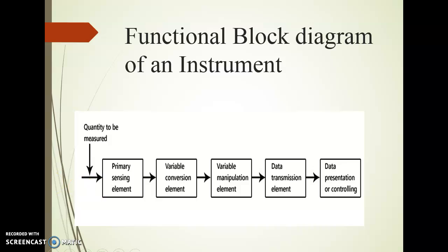Here the measurement is received in the form of non-electrical parameters, that is, most of the signals we want to measure are non-electrical in nature, such as pressure, temperature, humidity, force, and displacement. So by using these non-electrical quantities, we can do some processing. Here the problem occurs: how is the non-electrical quantity converted into an electrical quantity, because nowadays most technologies or methods are electrical methods? So we want to convert our non-electrical quantity into an electrical quantity.